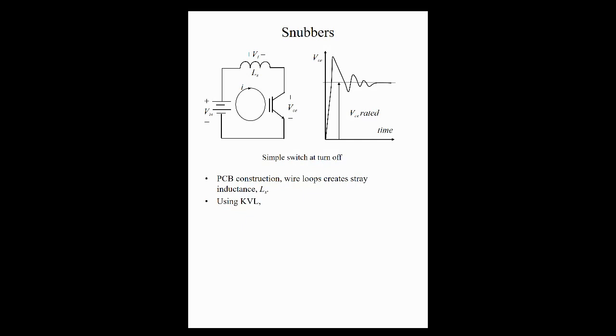What's the voltage drop across the inductor? It's given by VL. And we now have a voltage drop across our power switch, in this case, let's say VCE. And as we come across here, this will be minus V in. And this is equal to 0.